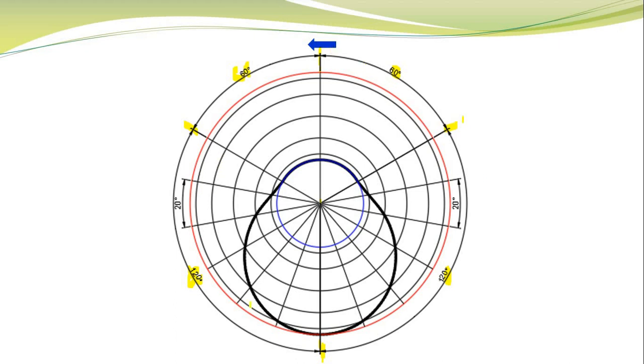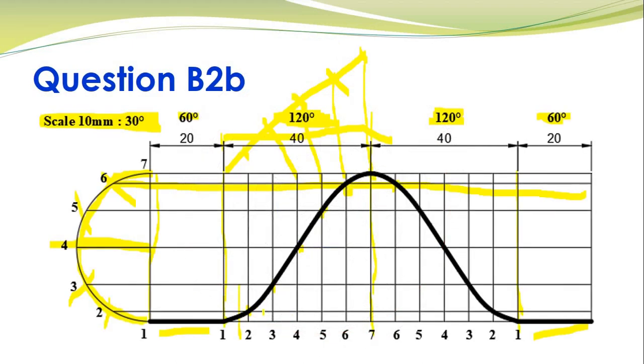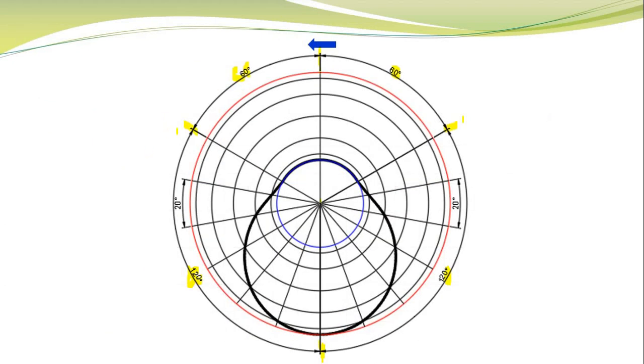Now between these 120 degrees rotation, with reference to your displacement diagram, I divided here into 6 equal parts, right? So 1 2 3 4 5 6. The same thing I need to do here. So you have to divide 120 degrees into 6 equal parts. So basically 120 divided by 6 gives me 20 degrees. So all of these increments in this region, right, that you see over here, are divided into increments of 20 degrees. So 20, 40, 60, 80, 100 and 120.